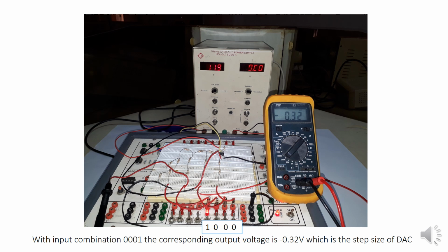So this 0.32 volts is nothing but the step size of our DAC. We can increase or decrease this step size by changing the RF value. If you want 6.4 volts, then you should use a 3 kilo ohm resistor, double this one.